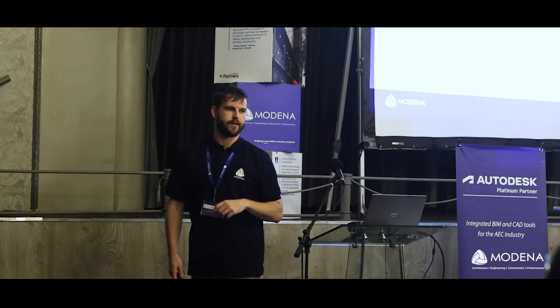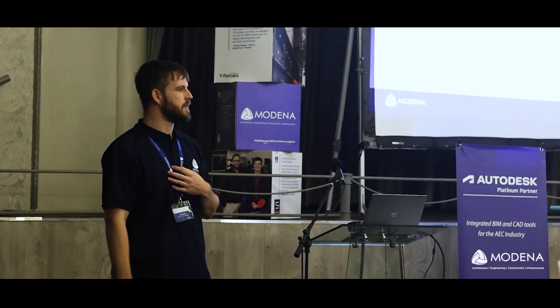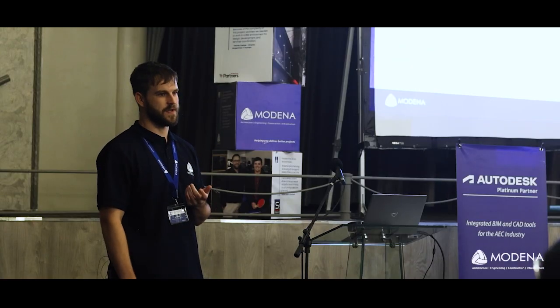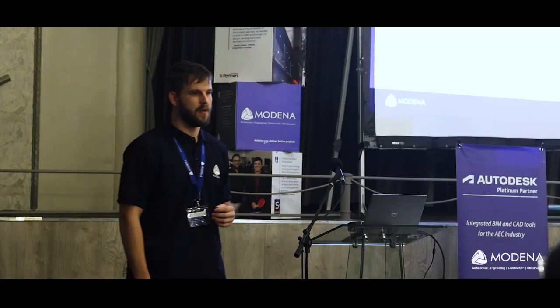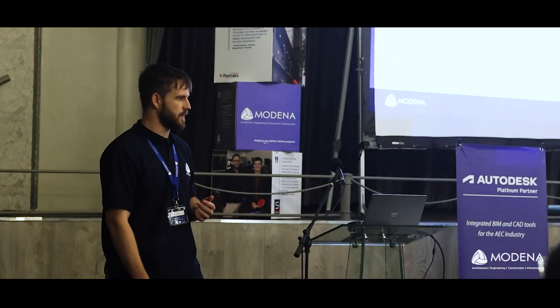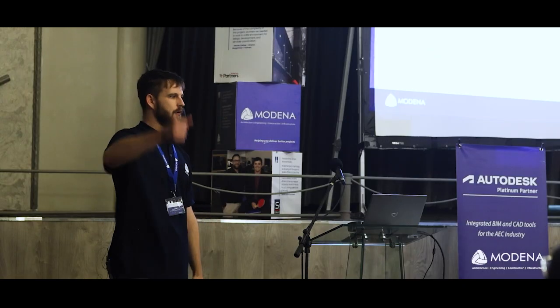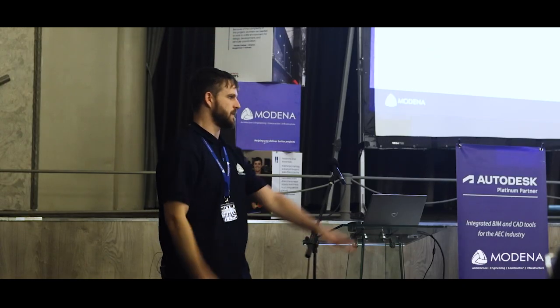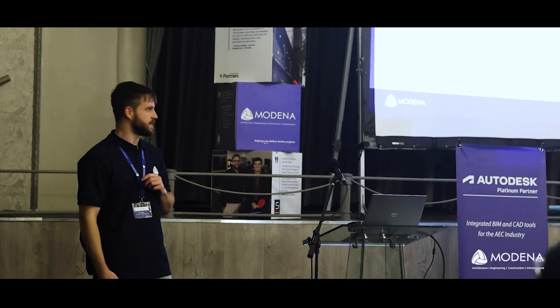So it might look right, you have this fantastic thing, it's saved you 3 hours. That would normally put a person in a complacent situation where you're happy. It looks good, but then you zoom in and you see your parking lot is 3 meters higher than what it's supposed to be. Or the entire model elevation, we're no longer sitting at 1345, but we're sitting at sea level. So just remember to double check those situations.